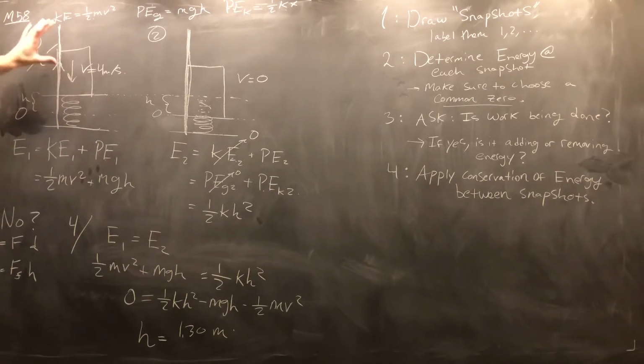But in fact, if it's oscillating like this, then the friction's acting the whole time it's moving. So, it's several distances that it's covered, several displacements that it's covered if that was actually happening. So we have to be careful we mean the total distance here, right? Because if it was oscillating like this, we'd have to add this part plus this part plus this part plus this part plus this part and so on. But anyway, here we just have one cycle, one oscillation. It's just moving down, so we can safely put h.